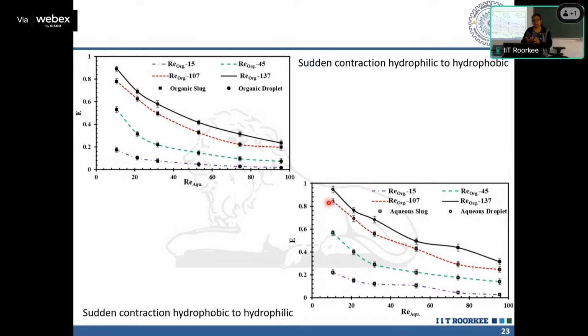If you wish to have a slug of low viscous medium, you have to figure out what the contact angle of the solid wall should be. So you have to design it that way. For our case, we can say it is hydrophobic and hydrophilic, and we have taken water and toluene. Maybe you are taking another solution, or targeting some other reaction or some other mass transfer operation.